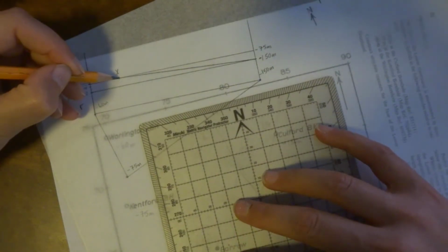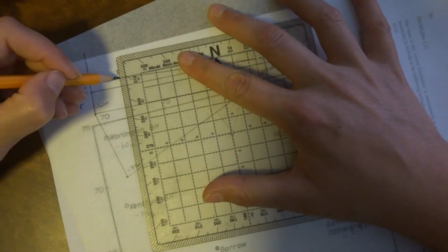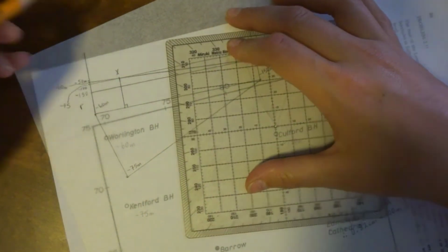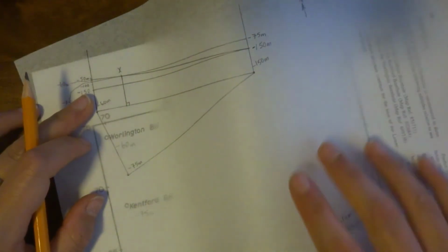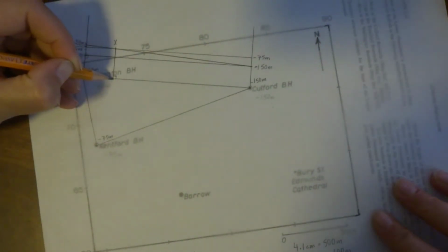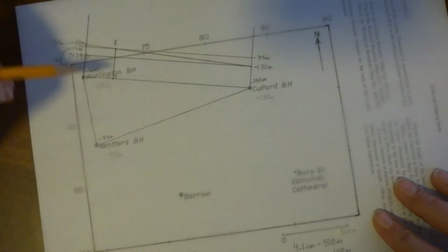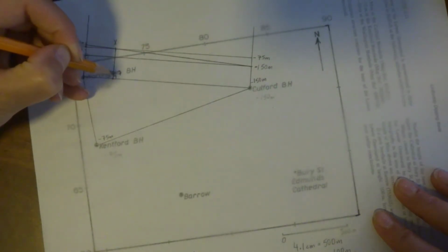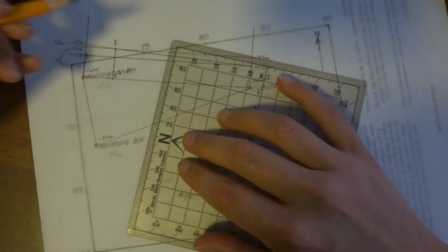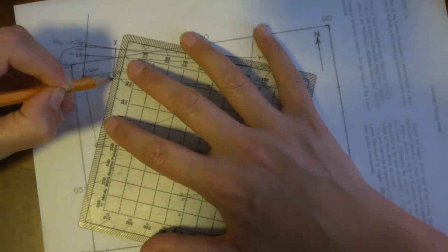So now we transfer point X back to our original triangle, making sure the extension line is perpendicular to that side of the triangle. I'll reposition the onion skin on the map here. So now we have the point X on the triangle between the minus 60 and minus 150 boreholes. That equals minus 75 meters. And we have all the information we need now to simply draw the strike line between these 2 points across the triangle.